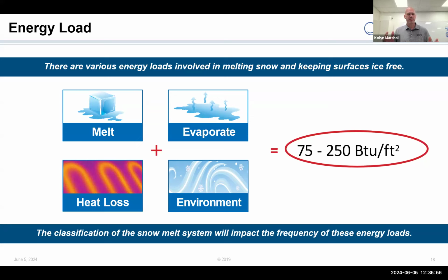Part of that is because I'm trying to compress that 18 inches of snowfall into the same amount of time from a consistency standpoint. So I'm looking at a 2-hour window of melting. So 6 inches and 12 inches or 18 inches all need to melt over 2 hours from a design calculation standpoint. The reality is in the field, my time is going to go from an hour and a half to 3 hours. It's a swag.